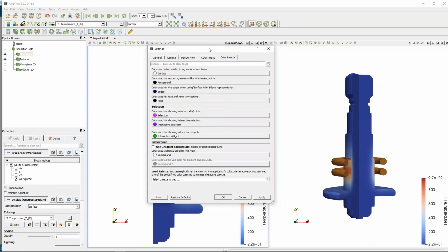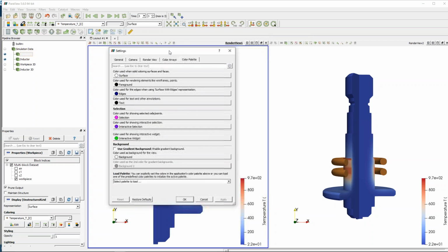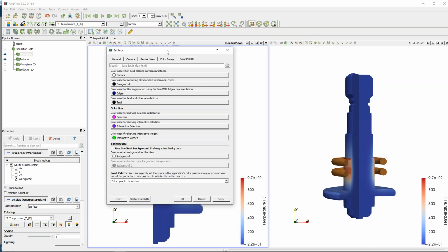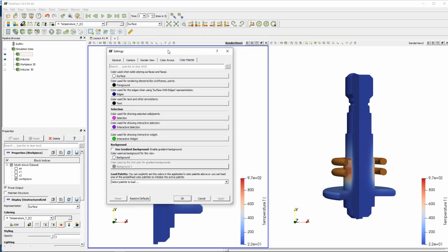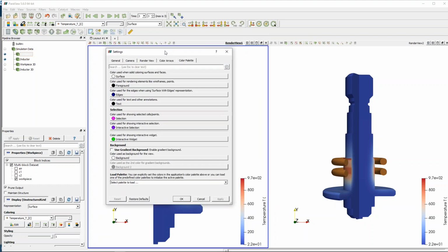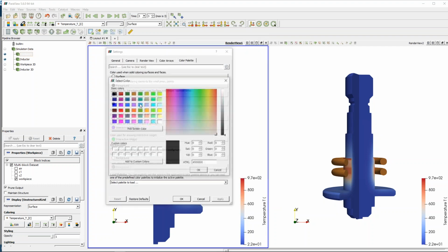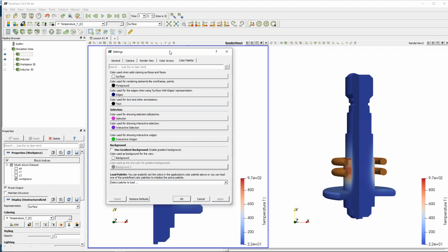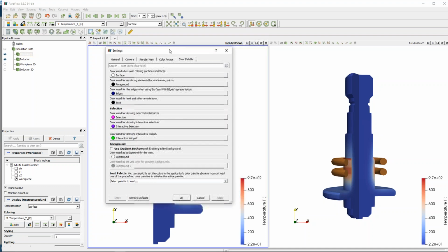This is one place you can do that, but I believe that you need to go not through CENOS, but separately. You open a separate window in ParaView, and through ParaView itself, not through CENOS. And then if you change these things and save them, they should stick. They should stick for all cases.